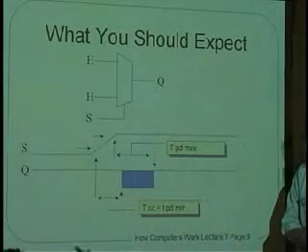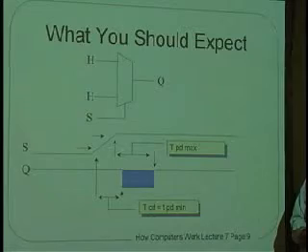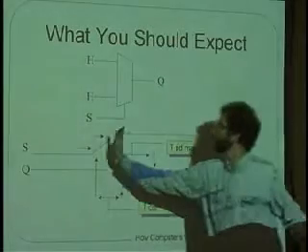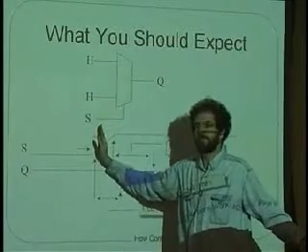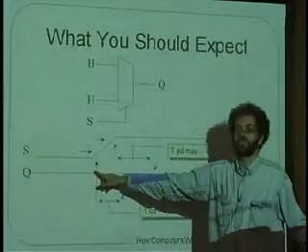However, yeah? I thought we had said the propagation delay included the contamination delay. If the slope of this line is infinitely sharp, okay, if this instantly goes from a 0 to a 1, then yes, they both start at the same time.